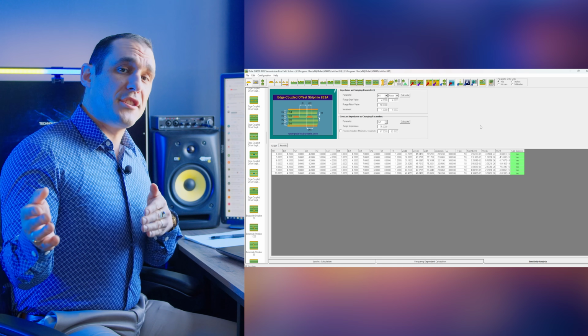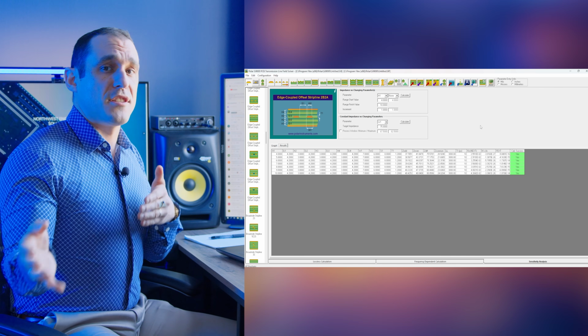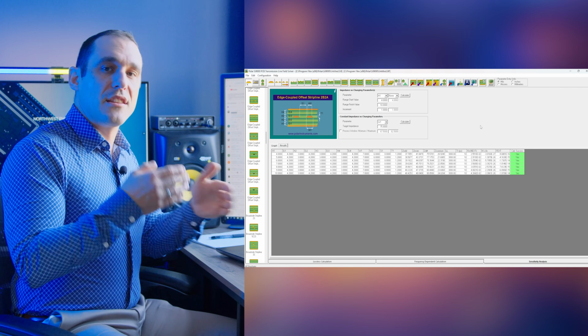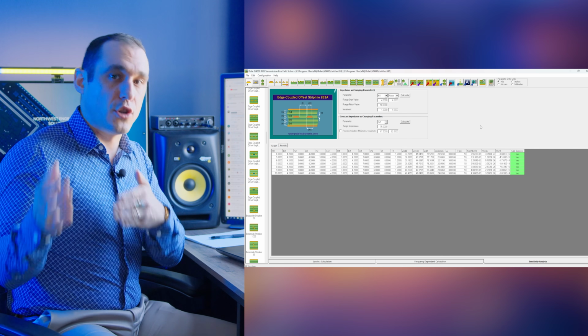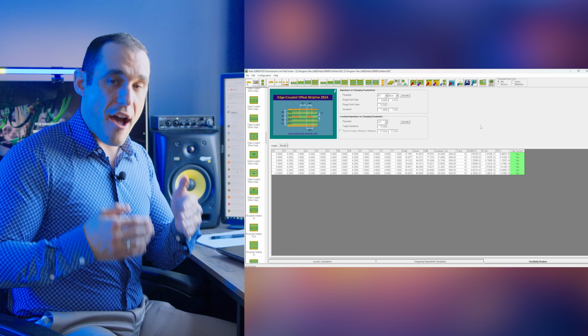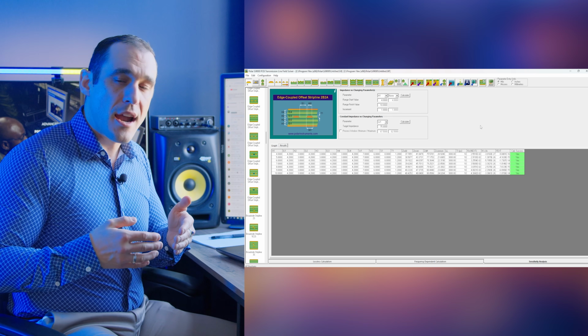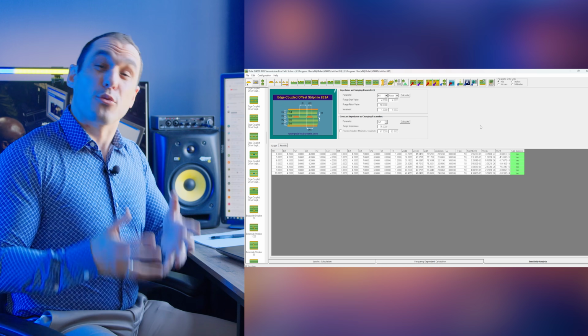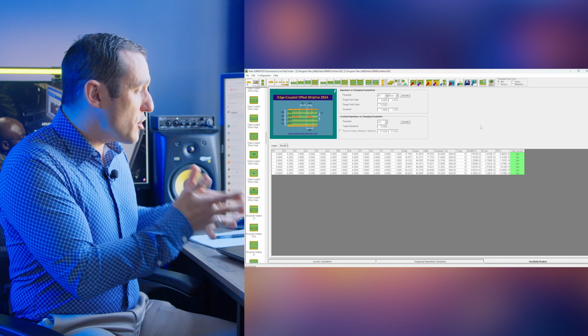There are some other things you can do inside of SI9000 as well, like for example, multi-line crosstalk. You can actually look at what is the forward and the backward crosstalk when you have multiple lines routed together, and that also helps you estimate the routing density that you can use in your design.